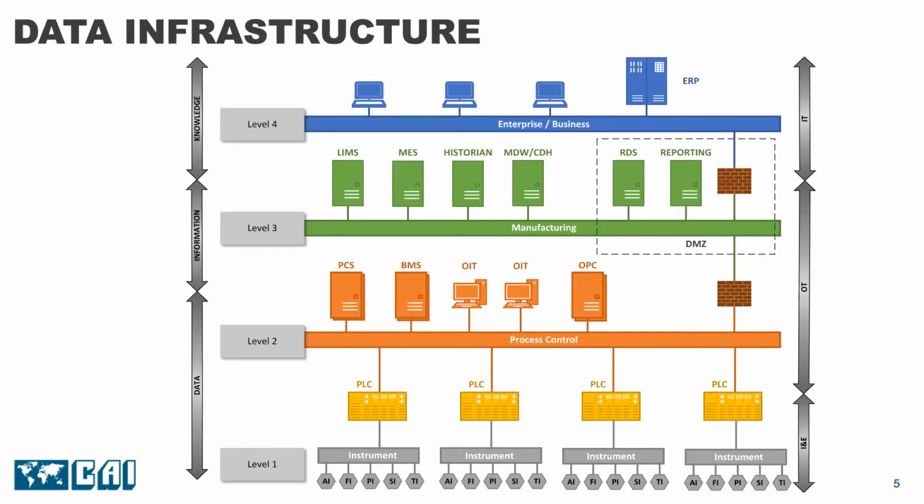In this diagram, IT supports business machines and enterprise software solutions. You may notice that there is no Wi-Fi on this diagram. Any of these networks can be extended with Wi-Fi. However, putting the field level instrumentation on Wi-Fi can cause problems, and you have to be selective with the instruments you put on Wi-Fi. This is particularly true if you have critical instrumentation.